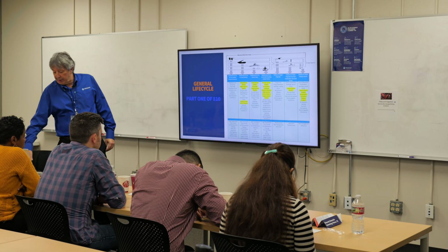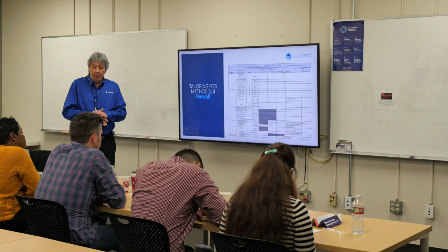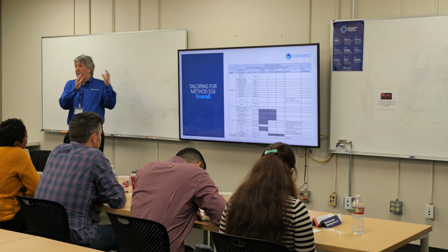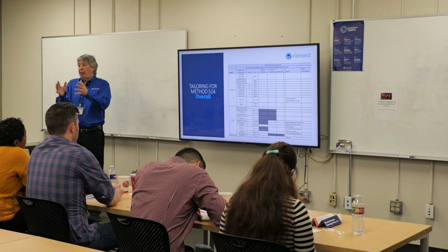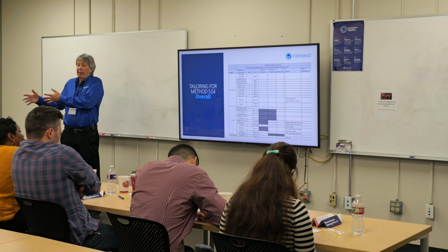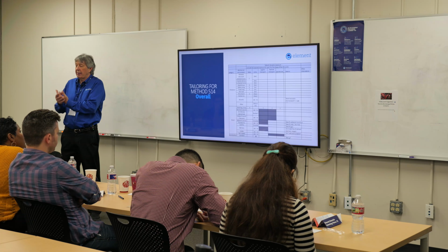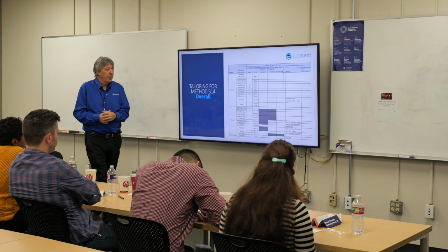MIL-STD-810 sort of tries to help you. There are these checks. MIL-STD-810 is broken into 3 parts. Part 1 is the front part, which is where this is from. Part 2 is all the testing. Part 3 is all the climate. So once you know what theater you're in, you can go to Part 3 and figure out what test temperatures you're going to do: cold, ultra cold, tropical, whatever it is.